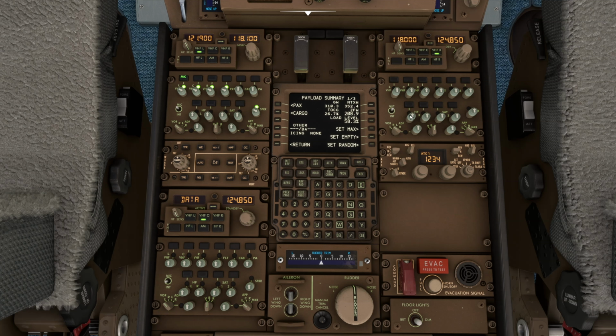FMC here is checked, and on the right side you'll put 1 to 1.5 on standby. So I'm gonna put 1 to 1.5, VHF left, center, right, flight, and the speaker. And above it will show traffic above us, and the squawk we got was 1611, so 1611 is set, and it should be on standby, and everything here looks good.